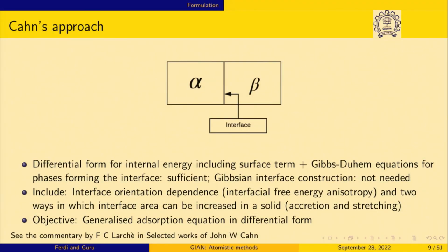Now, d gamma, if you cannot change the per unit area interfacial energy, which is the case in fluids, right, surface tension for example, you cannot change. I mean, you try to put more atoms and then it will again come back to whatever minimal area it is trying to do. In fact, that is how in elementary school you are taught why surface tension comes about, right. These atoms are sitting and they have these bonds which are not satisfied on one side, whereas in the bulk they are all satisfied. So, this excess is what results in surface tension, you have been told. That is not the case in solids.